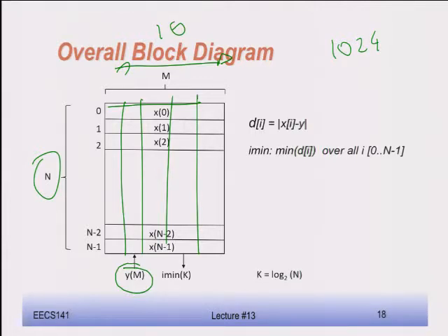So you have that distance, but now you have to do the minimum. That's where the challenge is going to lie. How do you compute simultaneously the minimum of 1024 words? I can build a giant block that has 1024 inputs, and out of this comes the minimum value. That's not the way you're going to do that. That would be a disaster. You have to bring all those words out. You have about 1024 times 16 bits wires, so that's 16,000 wires going in there, and suddenly 24 bits comes out with the minimum value. You don't want to do that.